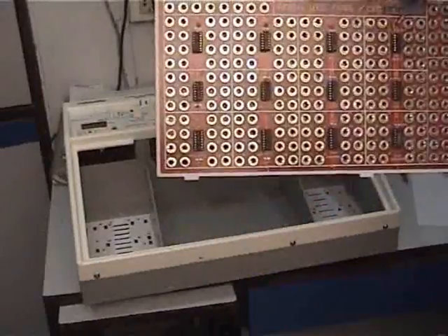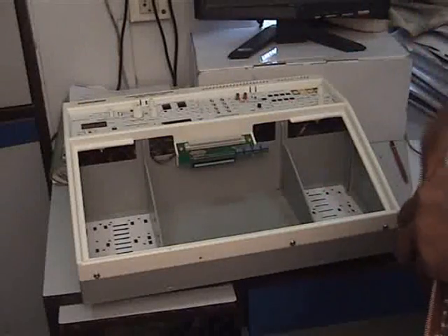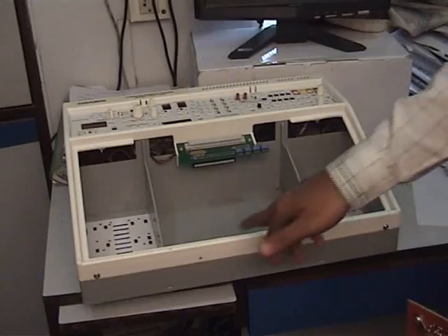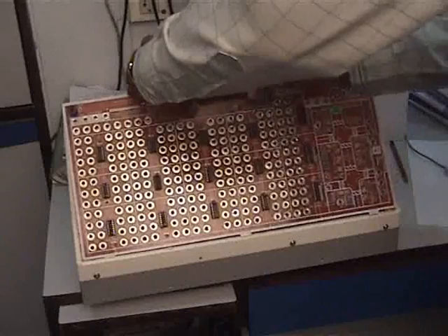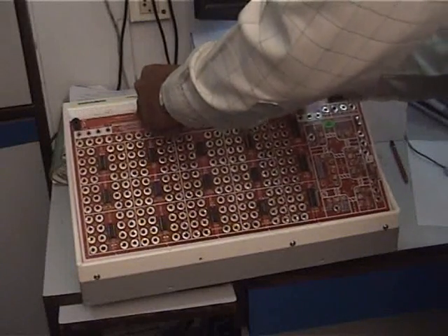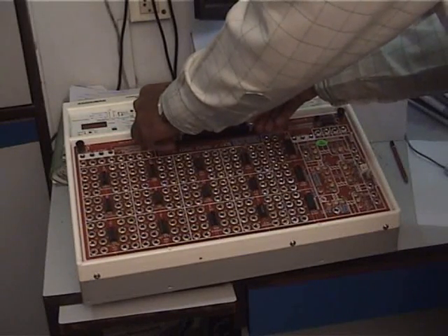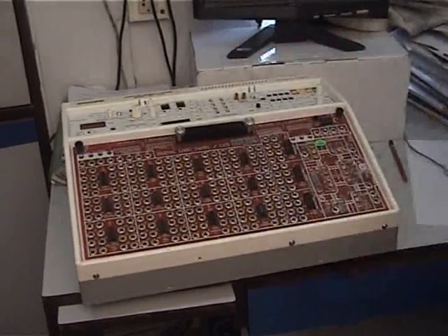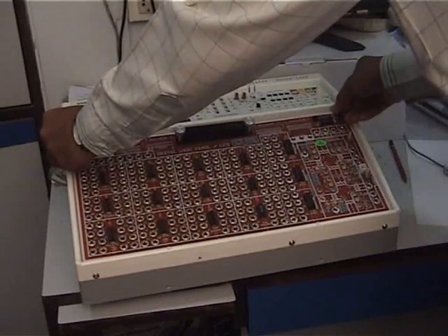It should be inserted in. This is CAT panel. It is a large size double side PCB. There are 2, 3 slots on the master unit, here, here and here. In this fashion, insert the PCB and push down the PCB to plug it into the 64 pin Euro connector. Lock the PCB using 2 keys located at upper 2 corners.